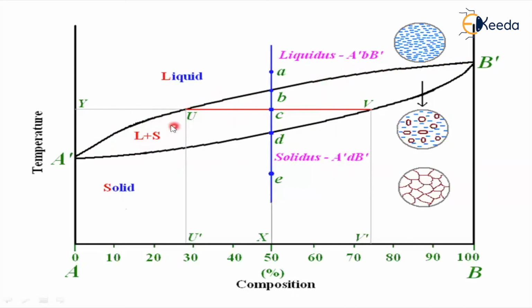And it is at the middle. After that, this curve is stating the solidification ending temperatures, or this is the solidification ending curve here, and this curve is represented as the solidus line. So that means the line between the liquid plus solid region and the solid region is represented as a solidus line.